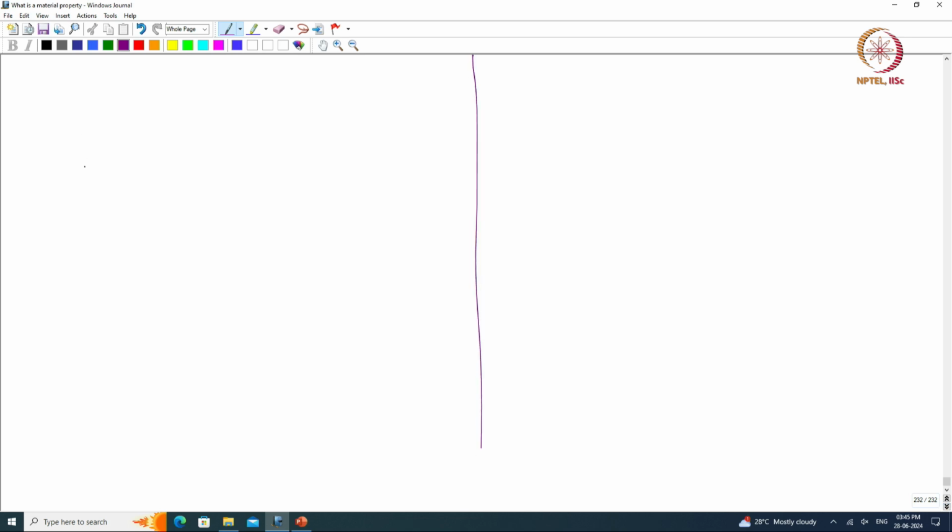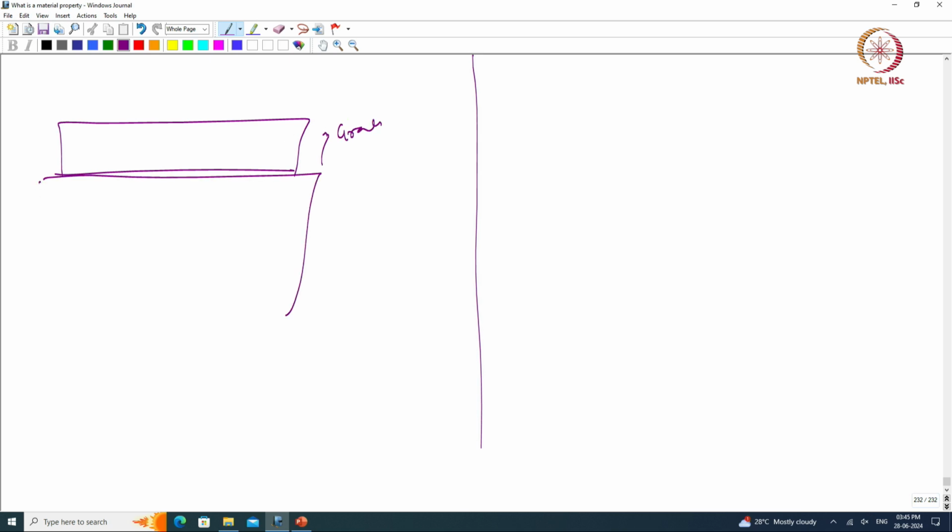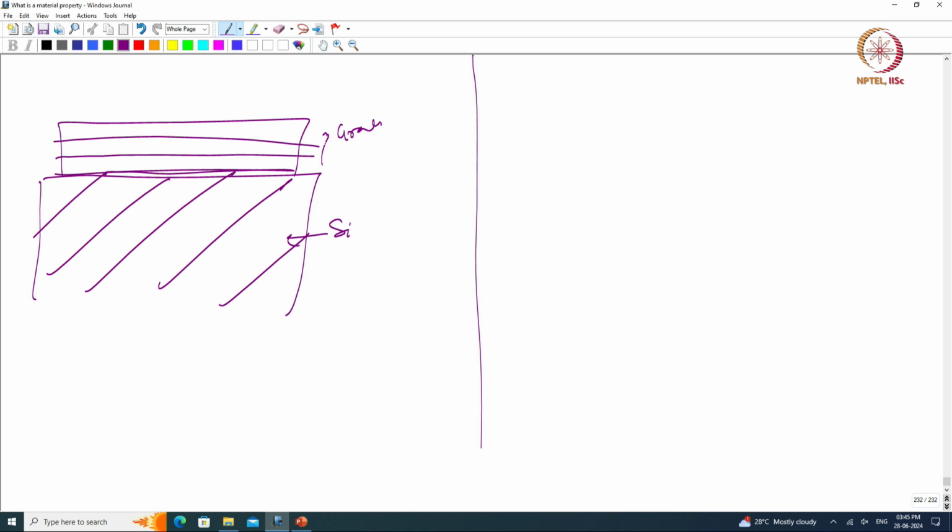Okay. So then what is the solution, right. So I said I have a thin film which is graded, I am just thinking out loud, right. So if I encounter such a problem, when I do research, what is a possible solution that I can envision? So there are all these interfaces, right. So I will design my material such that these interfaces are what are called diffusion barriers, right. So I do not let any diffusion happen through interfaces.